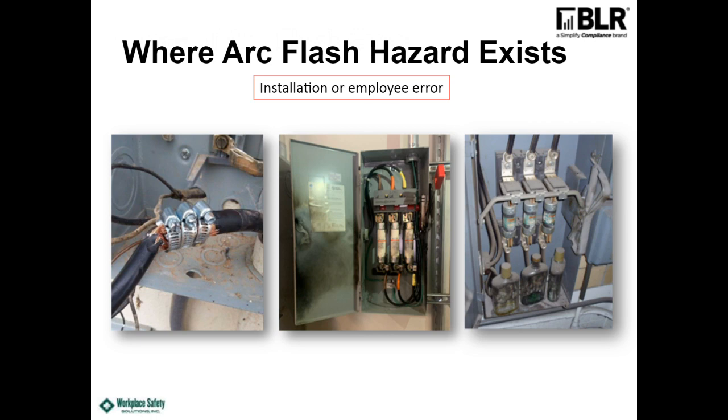In the middle, there were some wires to the right and behind the mechanism from that switch handle. That mechanism rubbed on those wires and breached the insulation, which caused this door to be blown open. The problem is that this is not a raceway on that side. The wires should have been run on the other side of the box. Some of these boxes will have a cover that you can use as a raceway on both sides, but this one did not. So you've got to go by the manufacturer requirements for installation, and it was not done that way.